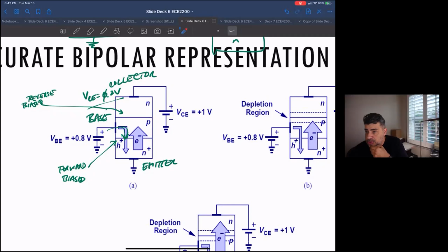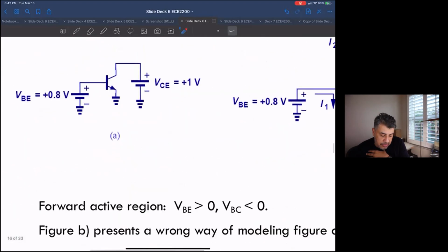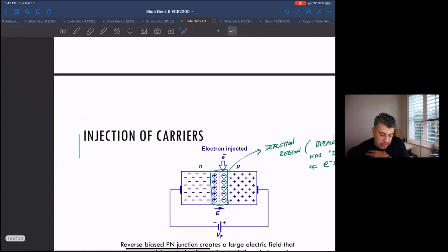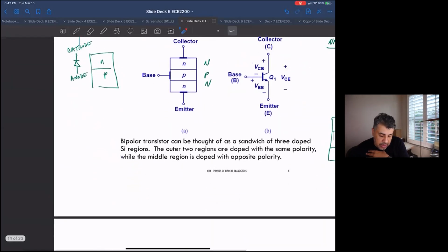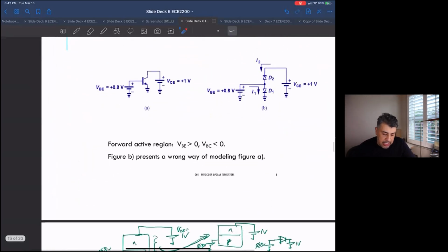So just to follow up with Melvin saying, the two major engineering choices in bipolar transistors: one is this separation, and the second engineering choice is the choice of doping concentrations. Like what is the value of this N compared to this P compared to this N. Notice that this says N plus. We didn't mention it before, but here is the first time we're mentioning it.